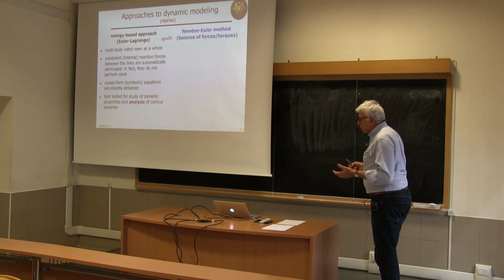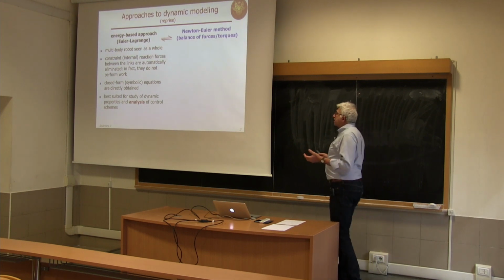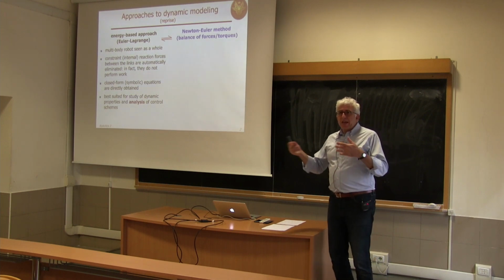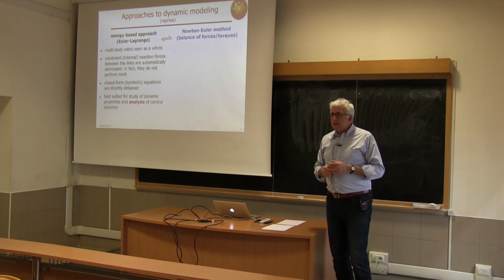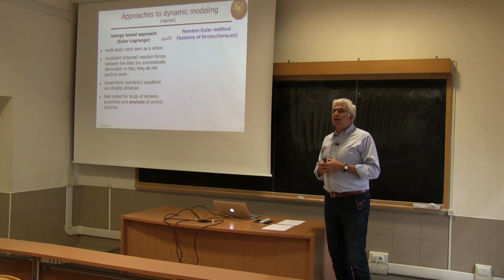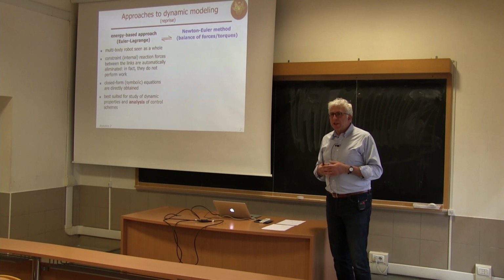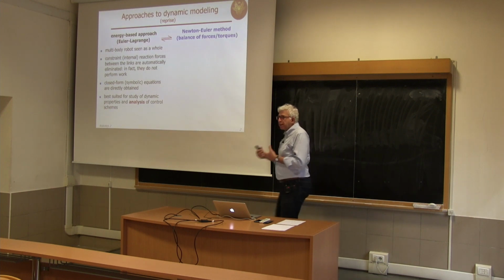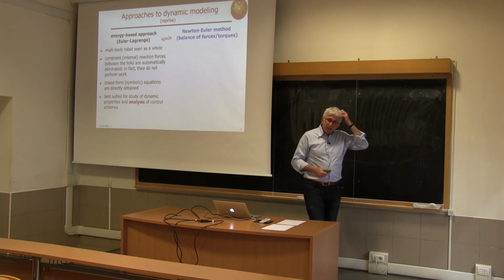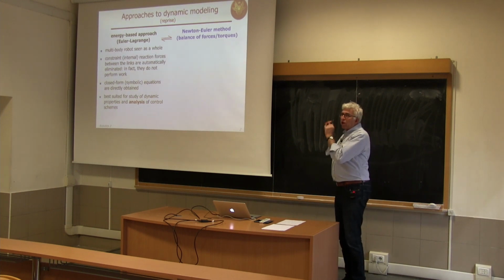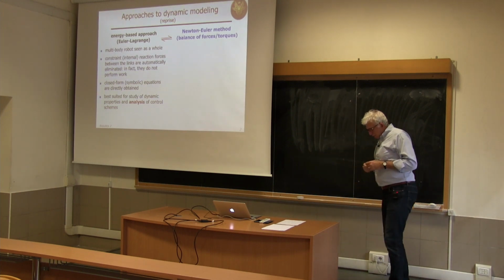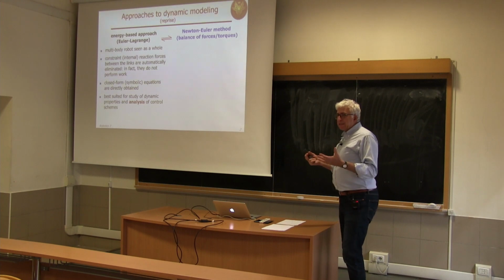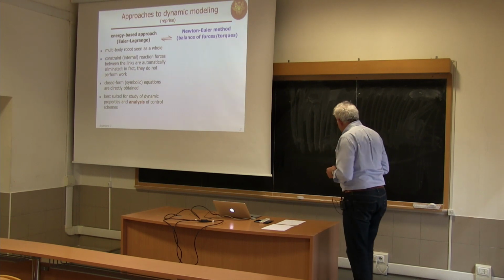So the Newton-Euler method, as we already introduced, is based on balances of forces and torques. Newton equation for a single mass m is just F equals m times the acceleration. If I had a body in pure rotation around one of its axes, I could write a similar equation in terms of angular quantities: inertia times angular acceleration equals torque. In this sense, this could be named the Euler part of the Newton-Euler equation, but this would underestimate the contribution of Euler to the picture.